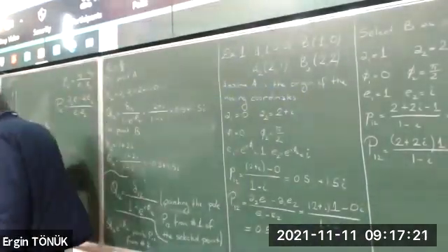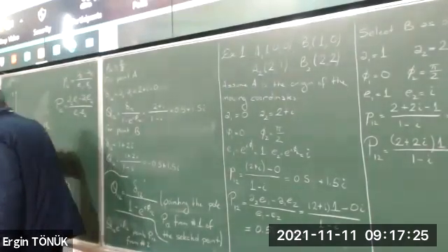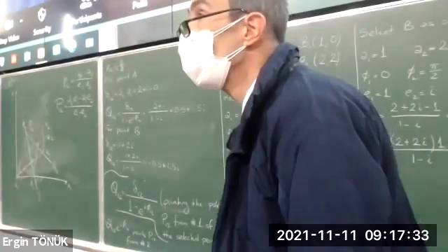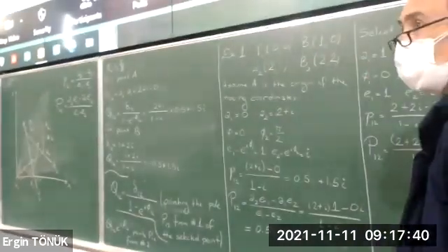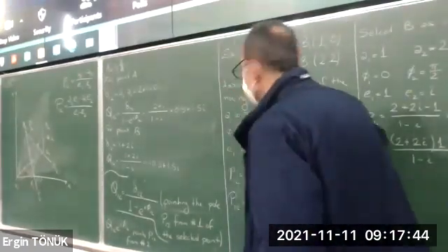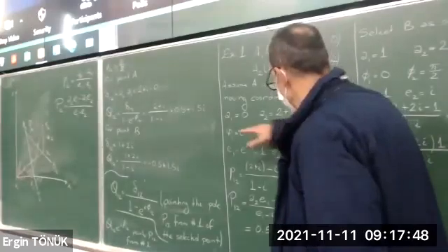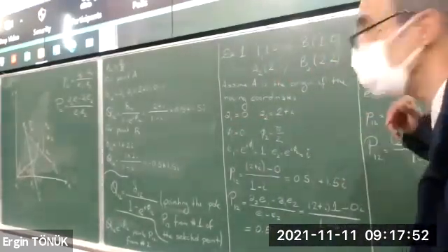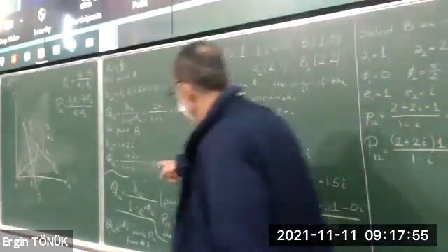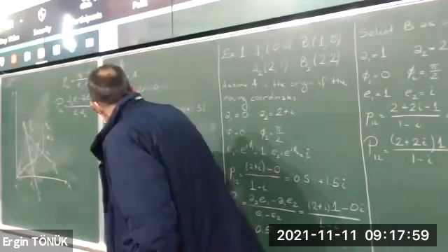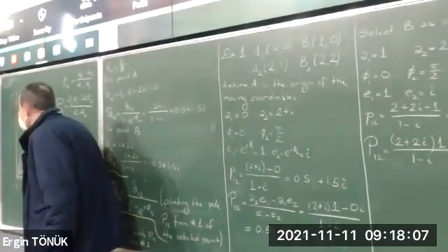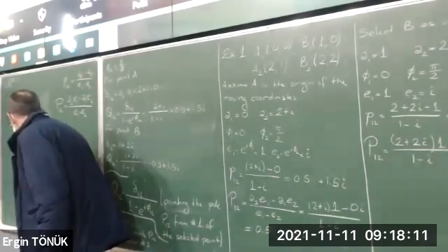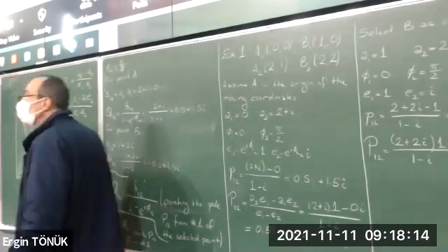Exactly, because from T you have to go -0.5 and then 1.5. Exactly, but what is different is positions of point B and positions of point A are different. Okay, so these make the difference. I'm not substituting the same A's and B's. Okay, and that's why this is the displacement of point B. This is the displacement of point A. They are different. Okay, A goes 2 in the real axis and 1 in the imaginary axis, whereas B goes 1 in the real axis and 2 in the imaginary axis. So the displacement vectors are different.